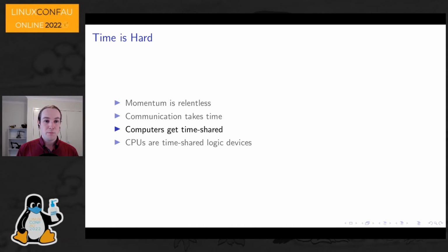Very often you need better timing resolution, so you need something to happen not just before some deadline, but at a specific time. If you've ever tried to use addressable LEDs on an AVR tiny processor and then do something else as well, you know it doesn't work. To get really good timing guarantees on a CPU, you need an ability for the CPU to drop whatever it's doing and respond to an external event, a CPU interrupt.